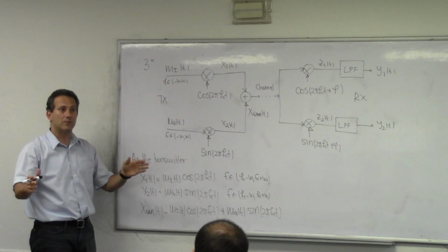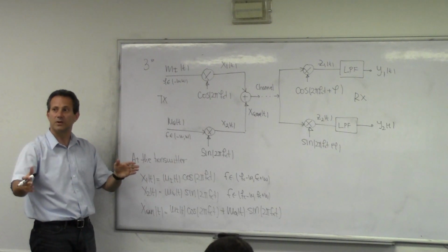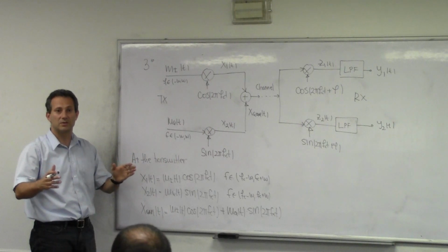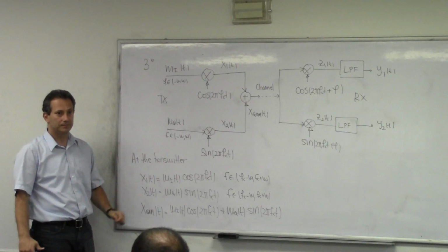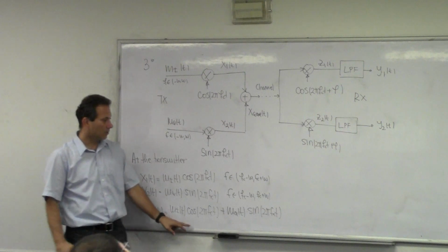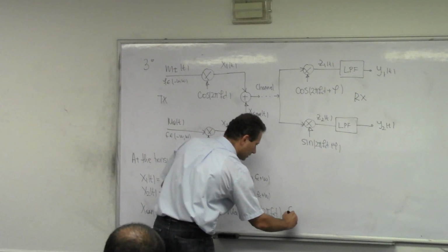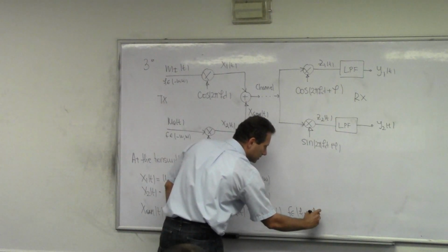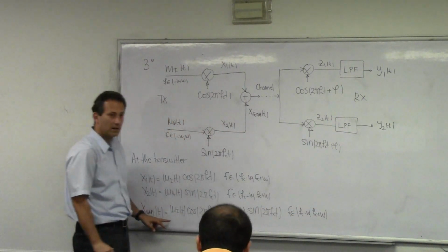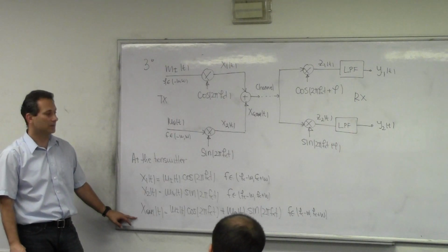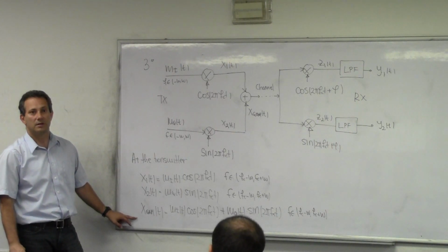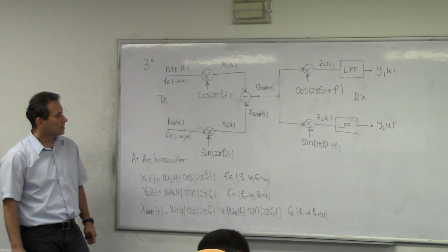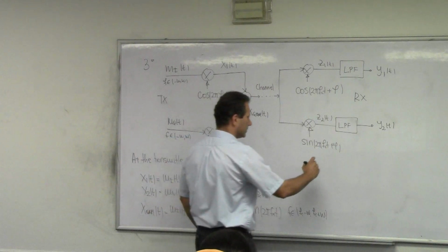But they're co-frequency, meaning they're in the same portion of the frequency axis, and they're co-time because they're using the same frequency at the same time, right? So this signal here also is in a domain between Fc minus W to Fc plus W, this signal as well, right? Because you have two signals that are in this band. When you add them together, they're again in the same band. Okay? So let's look at now what happened at the receiver.